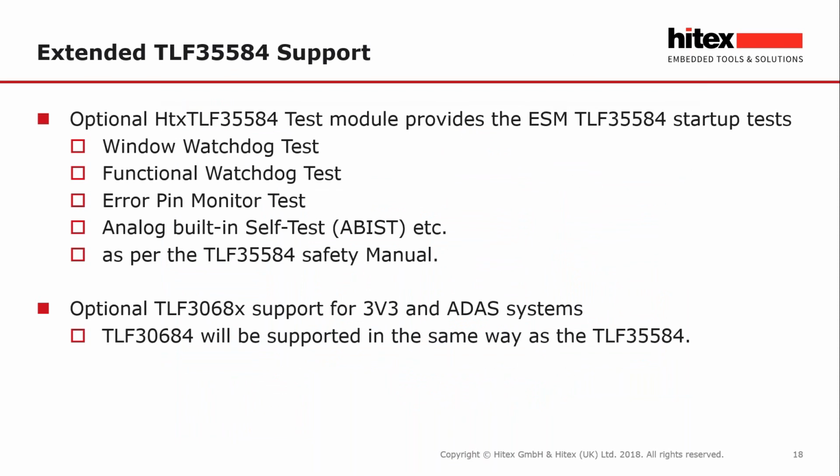Okay. Now, the TLF 35584 is critical here, and it has its own safety manual. So that safety manual specifies that certain things must be tested within the TLF 35584 before we can actually make use of it in a safety application. So we have to implement the window watchdog test, functional watchdog test, the error pin monitor test, and the analog built-in self-tests.